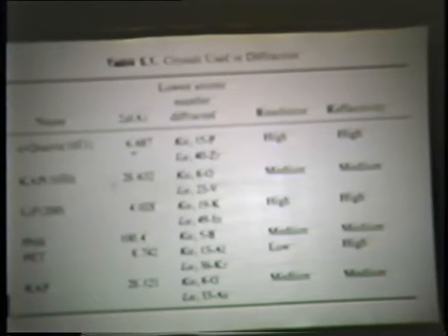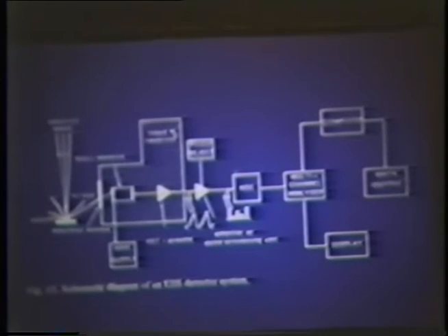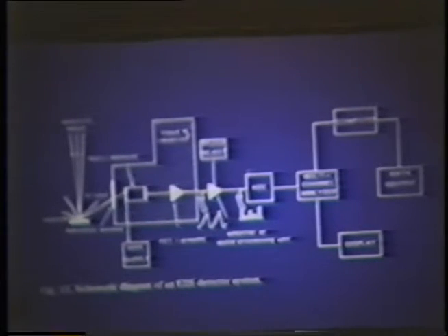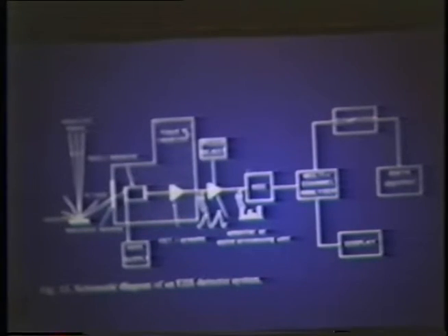The next slide, please. Now, the more frequently met type of instrumentation is the energy dispersive systems. These instruments take advantage of the fact that the X-ray photons also have quite discrete energies. We were talking about this a little earlier. The detector is a lithium-drifted p-type silicon crystal, which converts the incoming X-ray photons into a series of variable electrical charges, which can be amplified, measured, counted, and quantified.